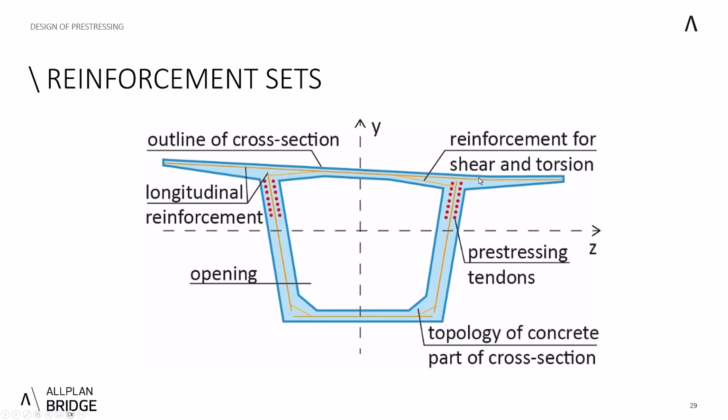It is assumed that torsional stirrups are closed with sufficient overlaps. Such stirrups can also effectively resist shear. The user can also select the option that longitudinal reinforcement is effective in transmitting tensile force caused by shear and torsion.